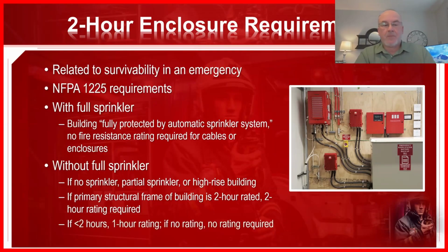If the primary structural frame rating is less than 2 hours, then it needs to be a 1-hour rating for this system. And if there's no rating for the structural frame of the building, and I'm not a structural guy, so I'm passing information along, then no rating is required, okay? I'm going to just leave it there and deal with other questions that you might have on a one-on-one basis or as they come up, because it is a confusing thing and you get various people telling you various different things.